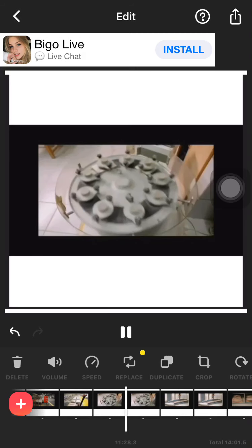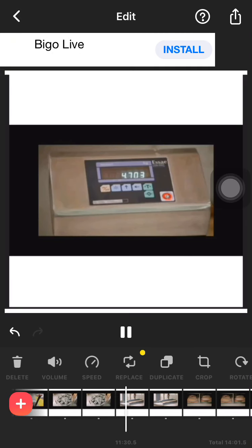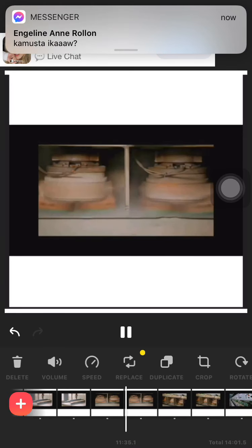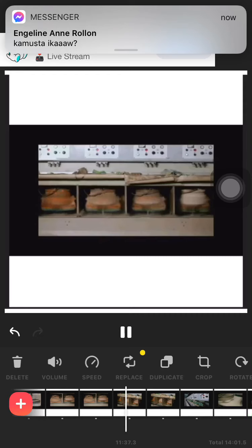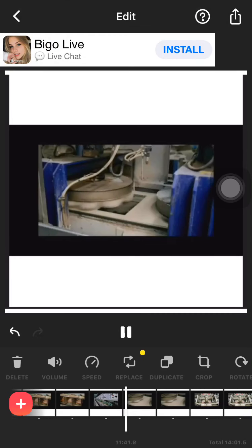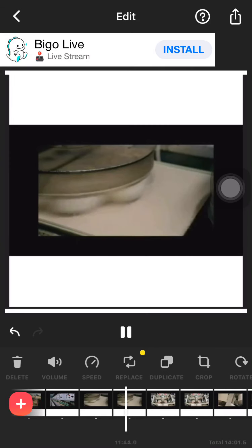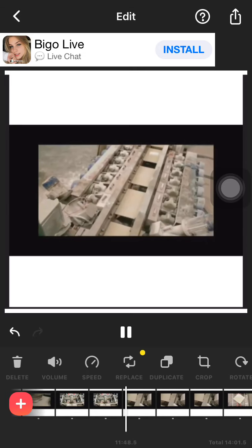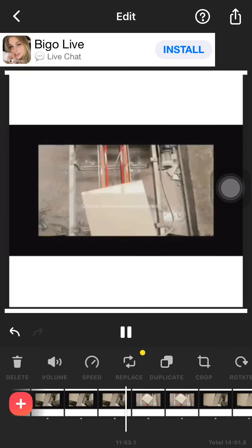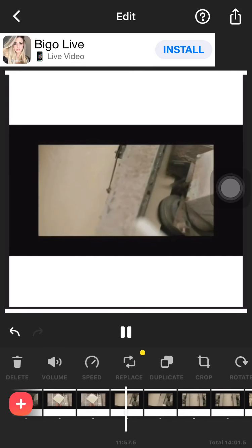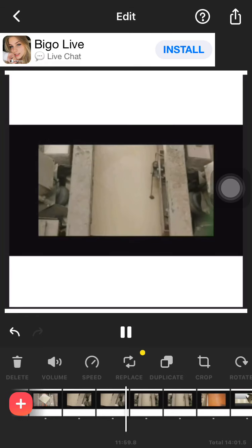After thorough quality testing of the batches at our special QC lab, tiles are given a further natural touch through Lapato polishing. 16 polishing heads, each with different abrasives, give each tile a unique natural texture and natural surface finish. The heat-treated tiles are then taken through a squaring and chamfering process, where a computer determines the size of every single tile and grinds them to give you reliably uniform size and complete dimensional control.